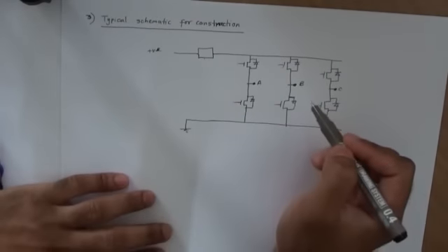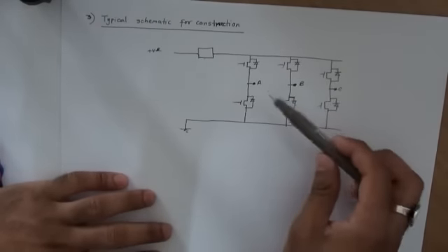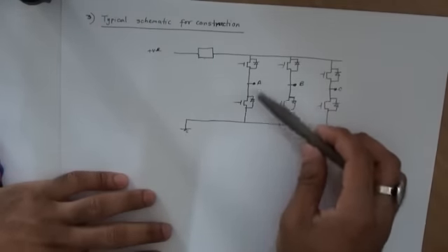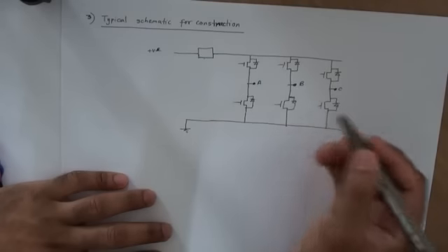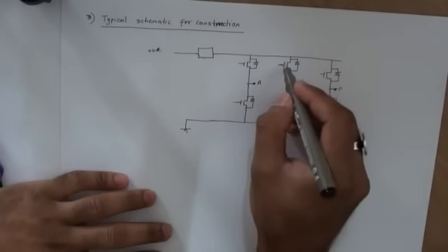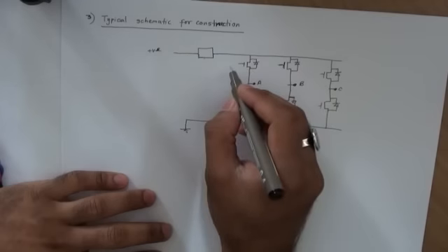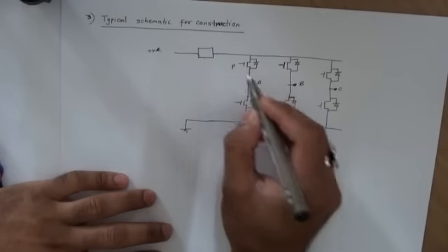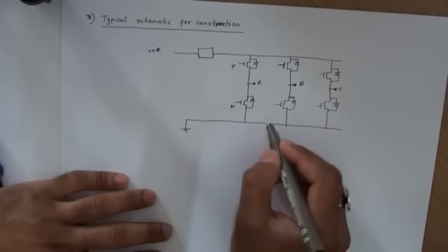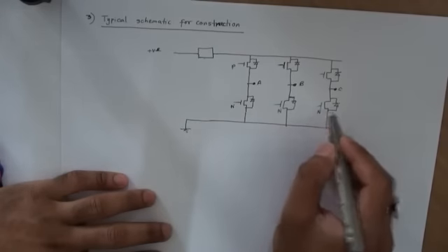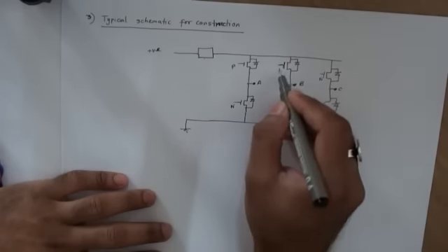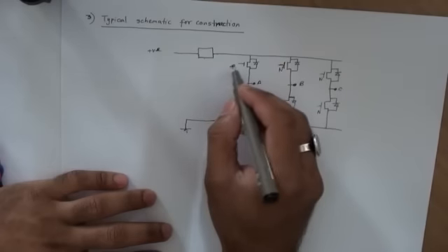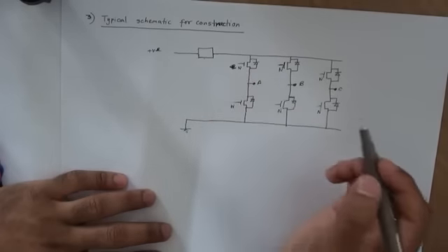To drive the motor, you may want to use the same type of MOSFETs. Sometimes people use different ones, so for instance they can use the P-type on the upper side and N-type on the lower side, but it's better to keep it all symmetrical and keep them all N-type.